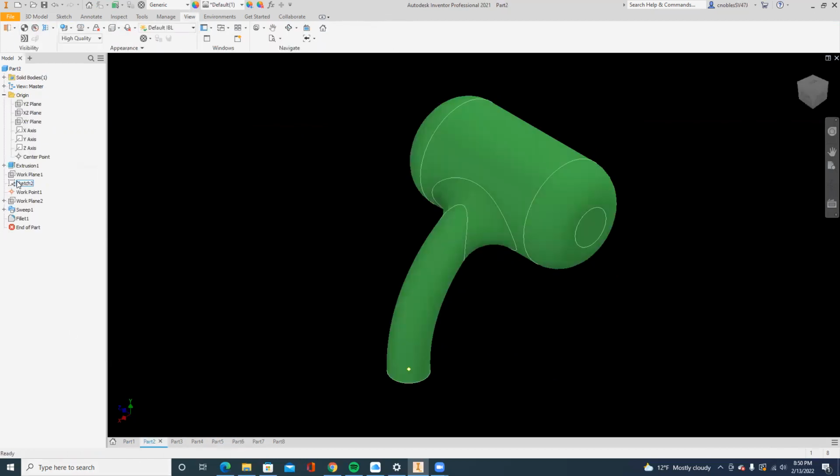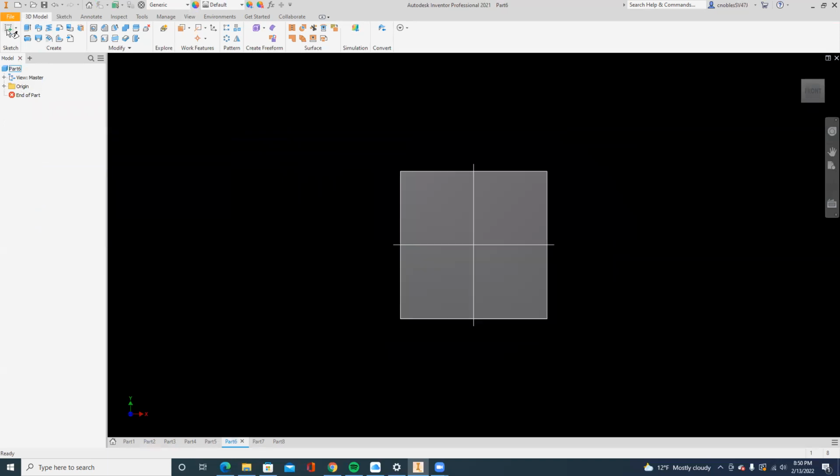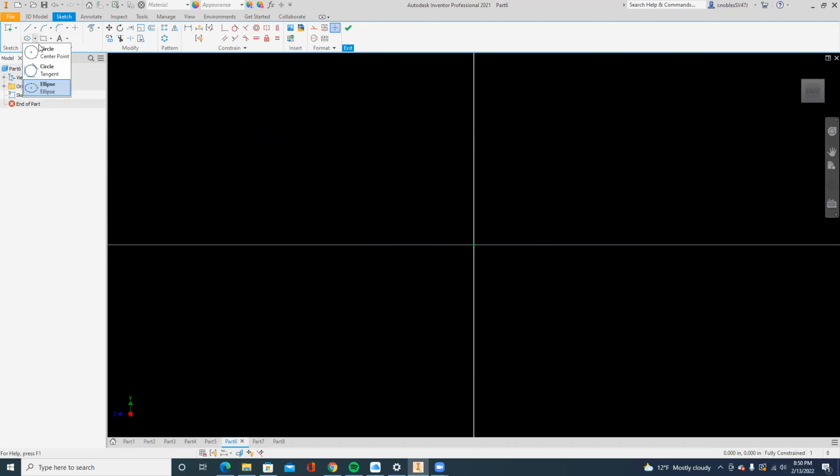Let's take a look at what's in it first, actually. So first things first, we're going to extrude a cylinder. Then we are going to sweep the handle and fillet it. It's really a pretty simple part, but the tricky thing on this one is going to be putting the sketches in the right spot. So first things first, I'm going to grab a plane here. There is some debate in the CAD community on whether or not you should start at the circle here, up here, up here, up here. It really doesn't matter too much.